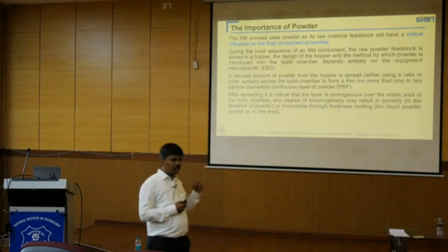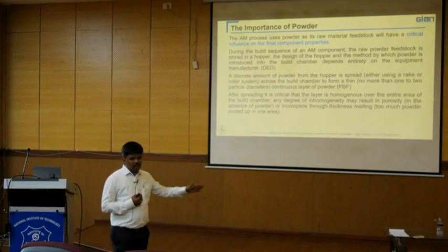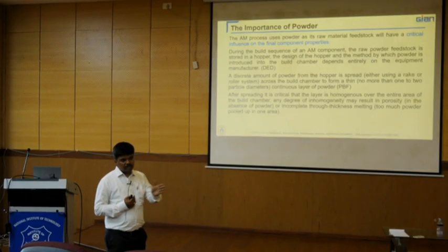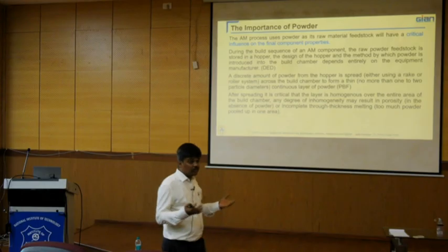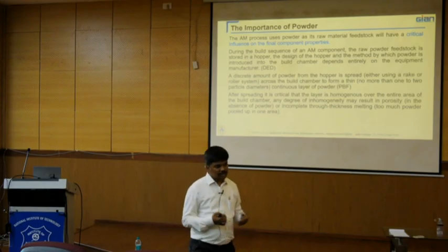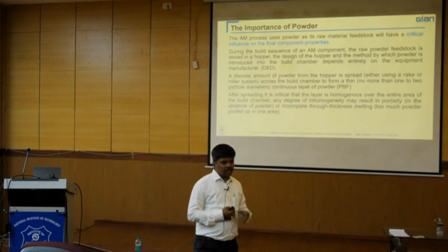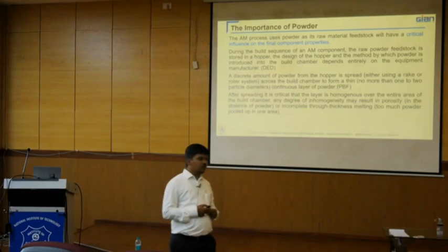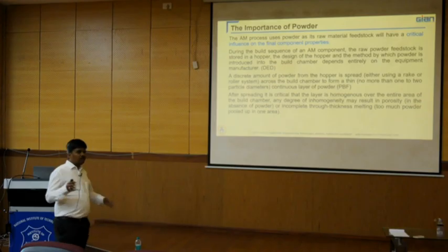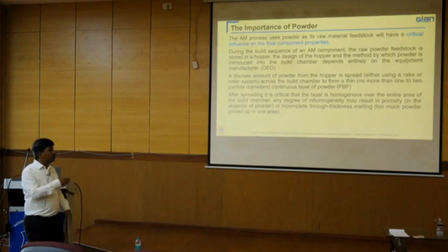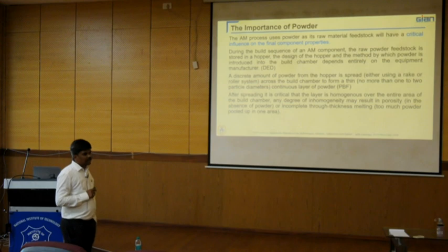But in the powder bed, your compacted powder will be spread by the doctor's blade or by the roller, and you will have so many packing factors. We expect one packing factor, but it is not going to be one factor. Depending on that factor's ratio, melting and solidification take place. Apart from the process conditions, the powder quality is also an important aspect.